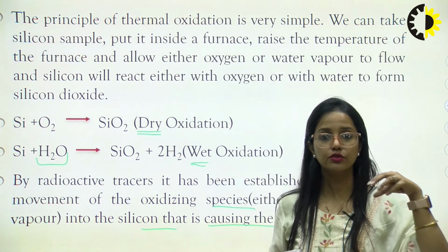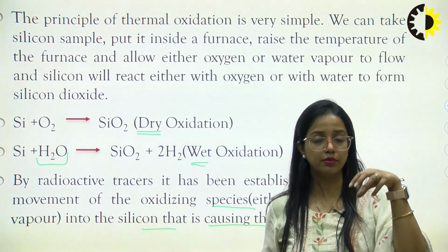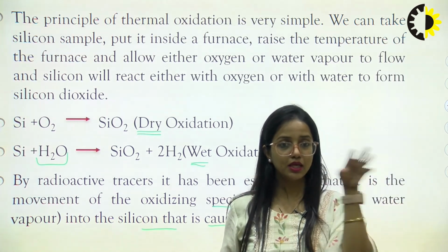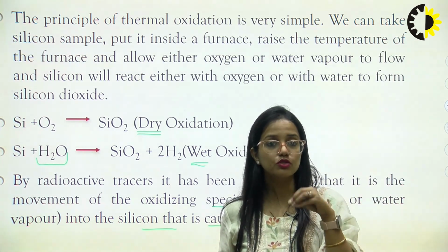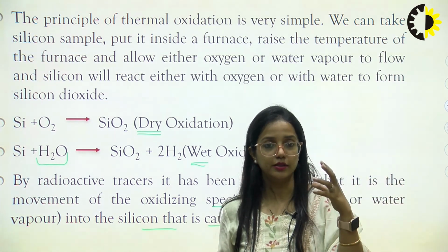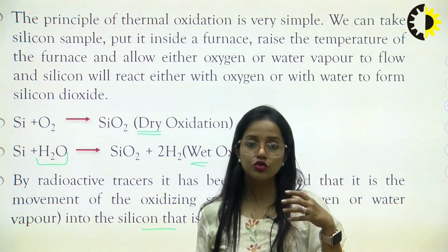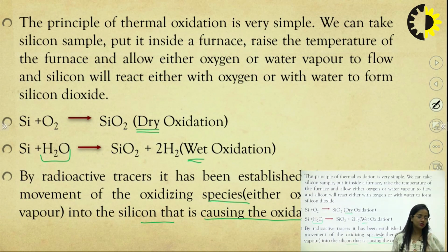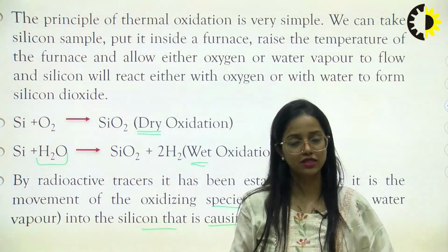So what we are actually doing is, let's say we have a wafer, and we want the p-type dopant added only at site A. So the adjacent sites, B and C, should not have the dopant. Just to make sure that B and C will not get the dopant, and only A will receive it, we mask B and C by doing oxidation. As simple as that. This was all about oxidation, and we will come up with more informative sessions in my next lecture.